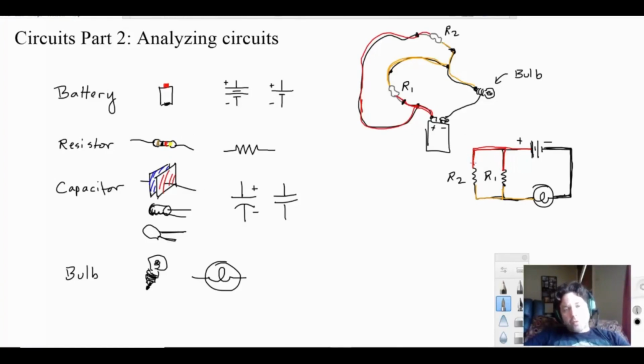But voltage through is a terrible way to talk about voltage, because it's a misnomer. Voltage doesn't go anywhere, right? And so it's not helpful to talk about it in terms of its motion. We either shed voltage, lose voltage, drop voltage, or we have voltage differences, right? So we have a 3 volt drop in that case from red to orange, and then we would have an additional 6 volt drop from orange to black. Okay. We'll continue that process and talk about the two basic types of circuits in the next video.